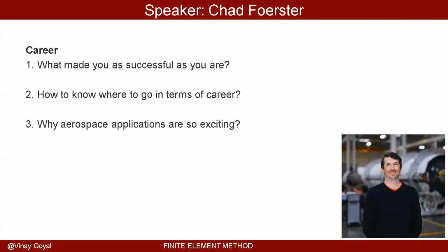Like, for instance, the Vega rocket, some of you might have known, just had a successful flight. I believe it was yesterday, coming back from an unsuccessful flight where they swapped two connectors. And so they basically had their thrust vectoring control backwards on the upper stage engine, and the whole thing just flipped and tumbled, and bam, you don't make orbit.